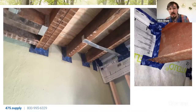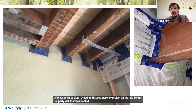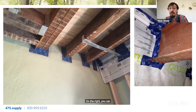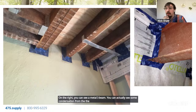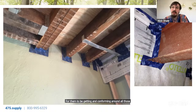Historic masonry project on the left. So this is a party wall that was treated with a fluid applied, and then they just taped where those joists were pocketed into that masonry to air seal that joint. On the right, you can see a metal I-beam. You can actually see some condensation from the thermal bridging of that metal. And you can see that it's a little bit more of a mess of tape for them to be getting and conforming around all those different edges and shapes.